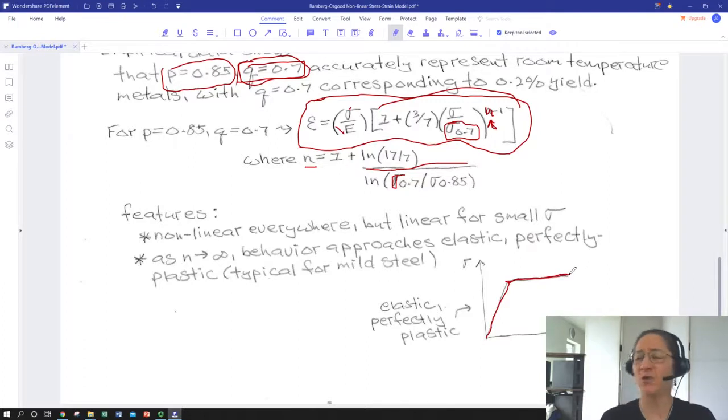It's like we don't need to apply any additional stress, practically, to get the material to strain like crazy. This is known as elastic perfectly plastic behavior, where we basically have a flat line of stress-strain beyond the yield. That's something that doesn't work harden at all. It just keeps going. You can smear it along with very little additional stress to get more strain. There are certain materials that will exhibit that, and that's important to know if you need to get something to move. It might have some consequences if we are designing against yield and maybe we don't calculate things right.